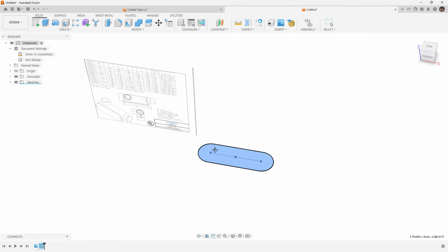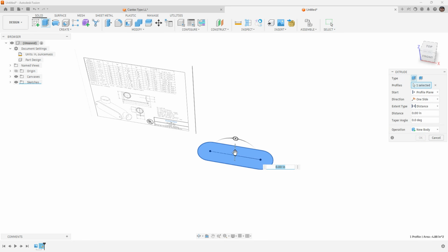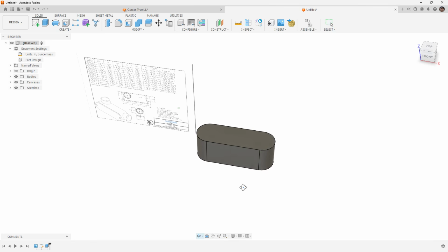Now we want to extrude this. I'm going to go ahead and pull this up. Typically, I use symmetry in my model, so I would typically do this as symmetric above and below the XY plane. For this model, it doesn't matter because I know that there's not symmetry in that direction, so I'm going to build it up in the positive direction. But this is something we always need to think about. This value is dimension B, so I'm going to have it linked to dimension B.